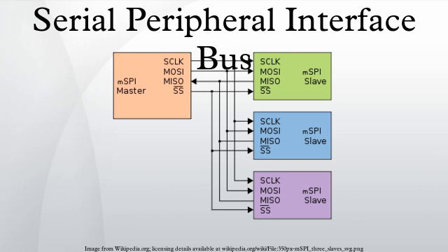3-wire serial buses: as mentioned, one variant of SPI uses a single bidirectional data line instead of 2 unidirectional ones. This variant is restricted to a half-duplex mode. It tends to be used for lower performance parts, such as small EEPROMs used only during system startup, certain sensors, and Microwire. Few SPI master controllers support this mode, although it can often be easily bit-banged in software.